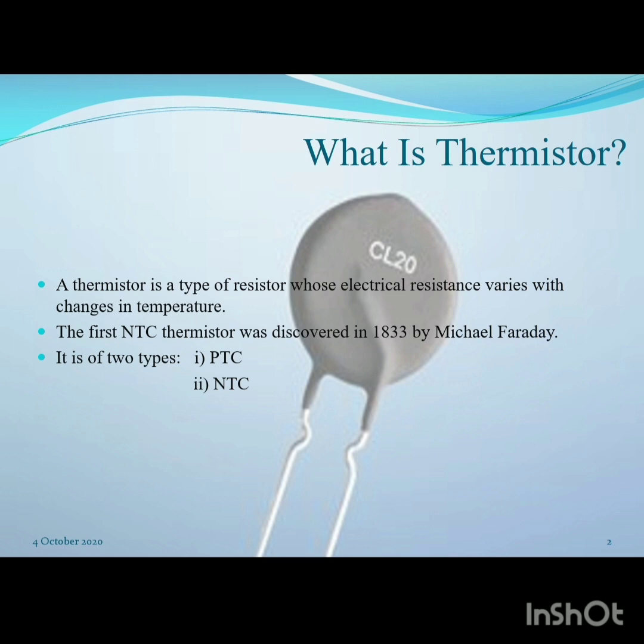So now, there are two opposite fundamental types, the NTC and the PTC. In the case of the NTC, the resistance decreases as the temperature rises. So there is a decrease in resistance when the temperature rises. The NTC is commonly used in temperature sensors or in series with a circuit as an inrush current limiter. There are many machines, but we are just discussing these two. So this is a brief description of the NTC.